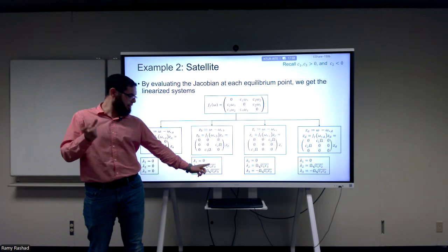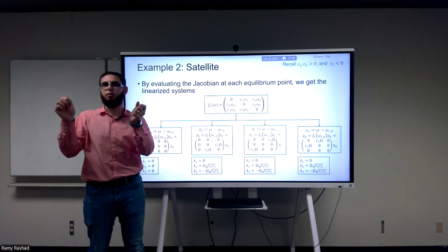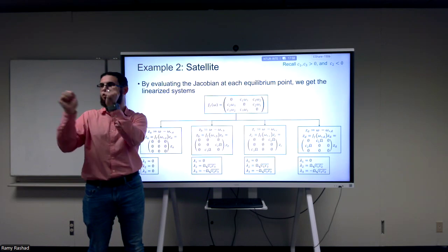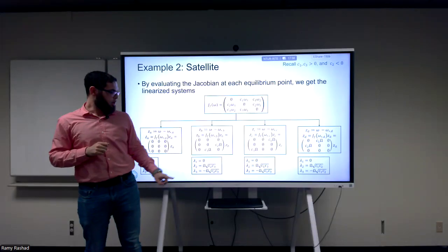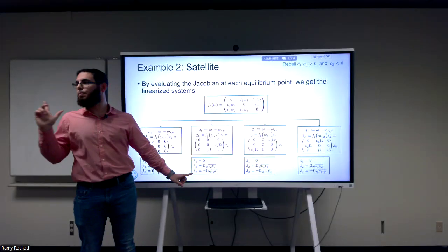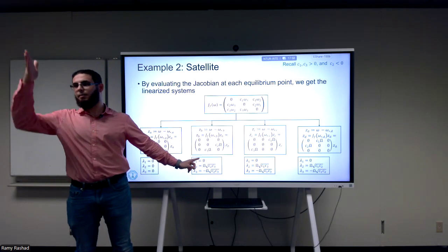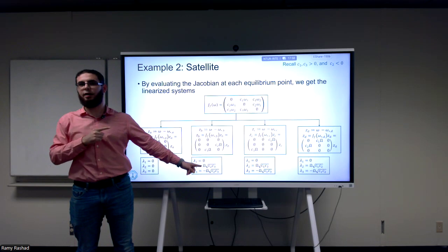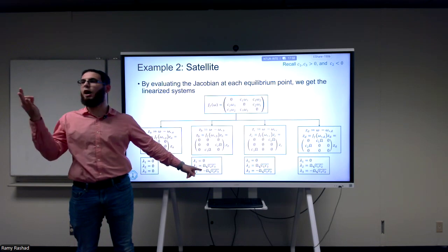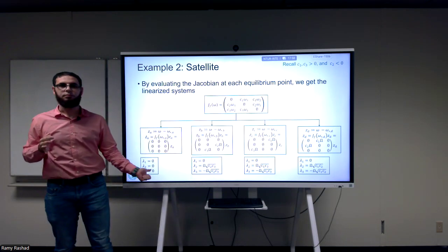So in the end, what do lambda 2 and lambda 3 correspond to? Complex conjugates, exactly. They are 2 complex conjugate eigenvalues of each other. So the real part of all of these 3 eigenvalues lies on the imaginary axis. Can we conclude anything from Lyapunov's indirect method? No, because we have 3 eigenvalues on the imaginary axis. We cannot say anything.